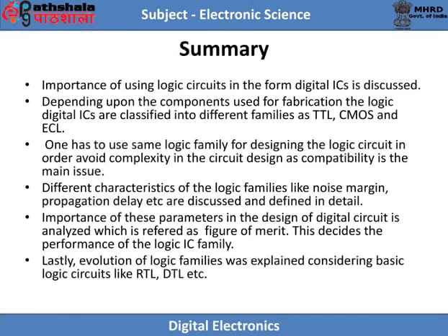Depending upon the components used for the fabrication, the logic digital ICs are classified into different families like TTL, ECL, CMOS, etc. One has to use the same logic family for designing the logic circuit in order to avoid complexity in the circuit design, as compatibility is the main issue.